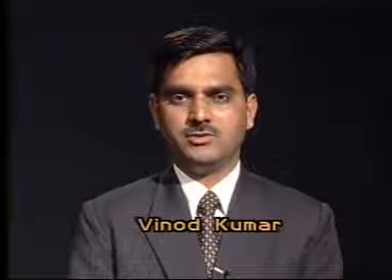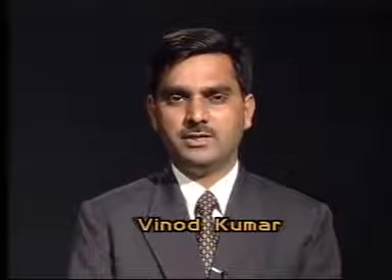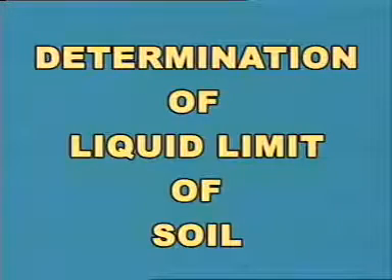Hello viewers, the liquid and plastic limits of soil depend on the amount and type of clay in a soil and form the basis for soil classification systems. The liquid limit of a soil is the minimum water content at which the soil is still in a liquid state, but has a small shearing strength against flowing, which can be measured by a standard procedure. In this program, we shall demonstrate the determination of the liquid limit of a given soil.